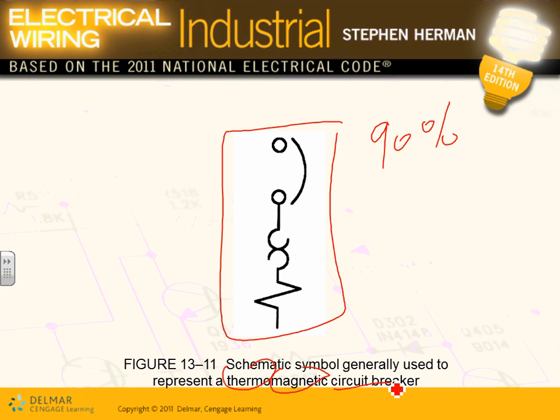That trips based on overload. Everybody understand that one? So this component here, guys, provides overload, and this component short circuit and ground fault. Cool? So, Karen, you're looking at a thermomagnetic circuit breaker right here in my hand. Any comments, guys? Any questions about thermomagnetic? That's where the term came from, thermo. It depends on heat as well as magnetism to trip the circuit breaker.